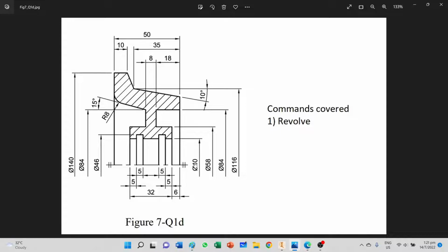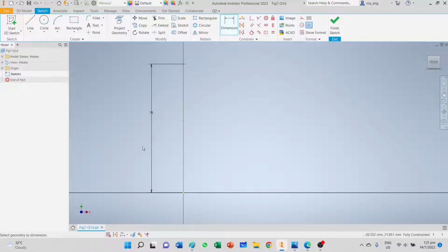But when you see this center line symbol with the two lines like this, it means that this is a half drawing representation, meaning to say that this whole image can be reversed on the other side, and the entire diameter of this component is 140 millimeters. Okay, so because we are just drawing half of it, that's why I started it at 70 millimeters.